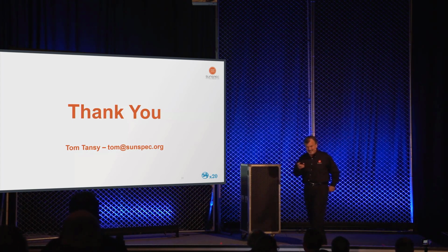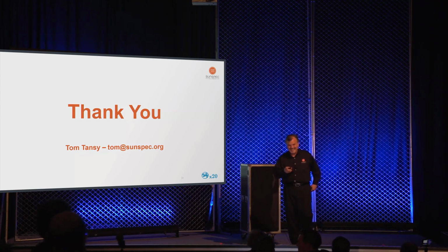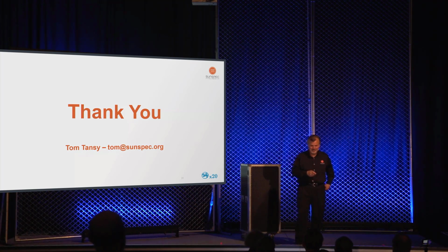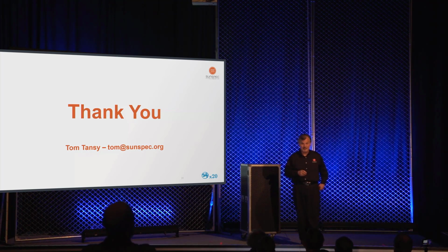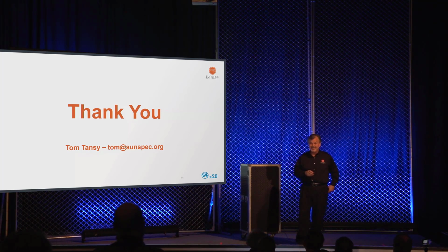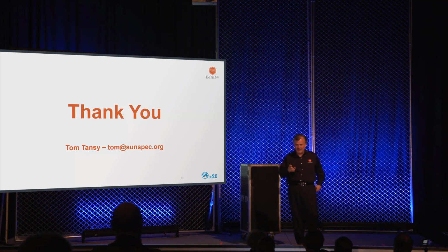Sure. Great question. You probably read the spec. Yeah, the certificates for the 2030.5 spec, they never expire. About 100 people have asked me, "Well, how can that work? And why did they do that?" Well, the concept was that this standard would apply to thermostats and other types of devices that nobody had ever opened up. So the certificates, frankly, are used for identity management primarily.